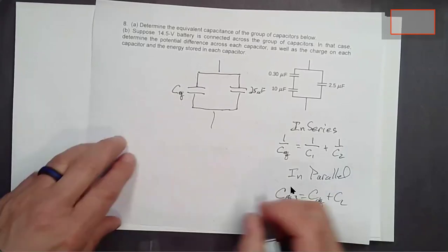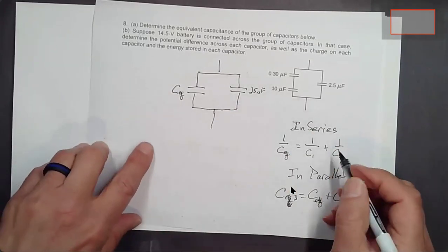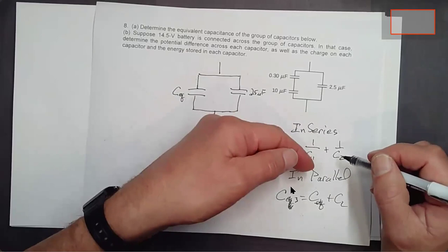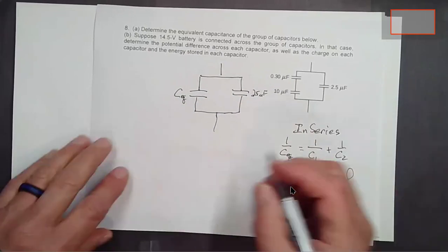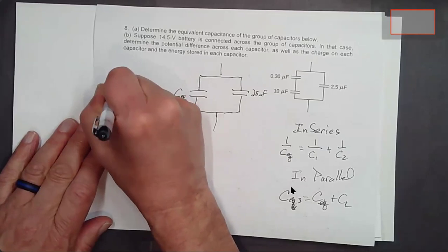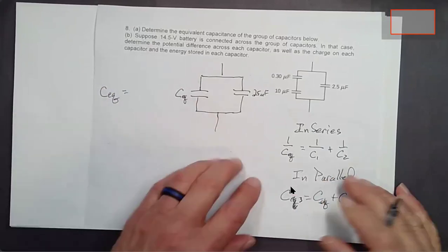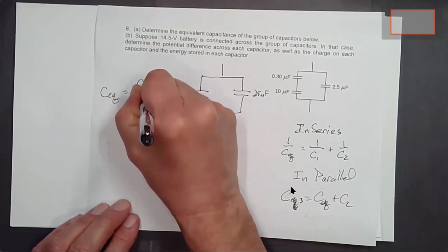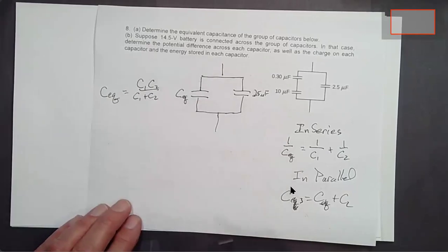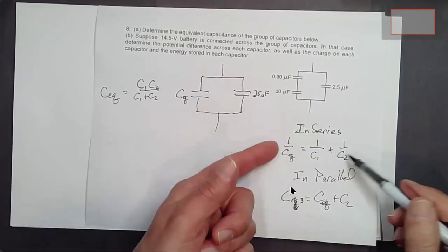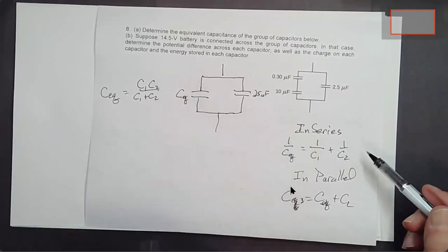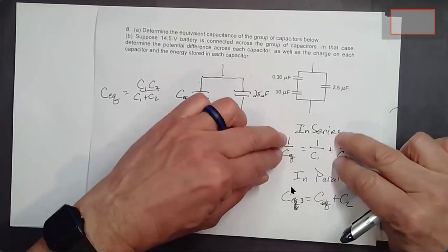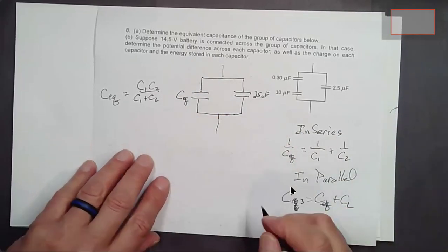And when I just have two capacitors involved in this thing, I can write this as C2 plus C1 over C1 C2. And actually C equivalent for just two capacitors will equal C1 C2 over C1 plus C2. So you can convince yourself of that if you play around with this. Get a common denominator, add them together. Then you'll have a simple fraction. Reciprocals of simple fractions equal that. So that's what it'll equal.